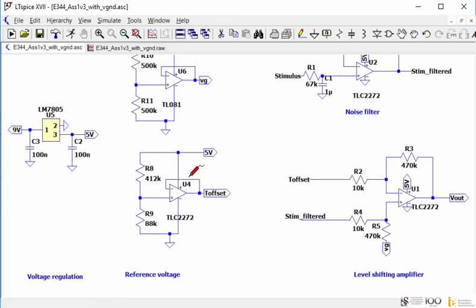So again, I use the voltage follower, unity gain, so that I can protect the voltage levels here. For if I did not have this unity gain here, these voltages would be affected by this one, but that'll be steady. And then because this V out may vary, it'll feed back and affect this voltage here. So I'm protecting both sides essentially. I'm protecting them against one another using this buffer. So it's compartmentalizing my design essentially. Nice and protected.